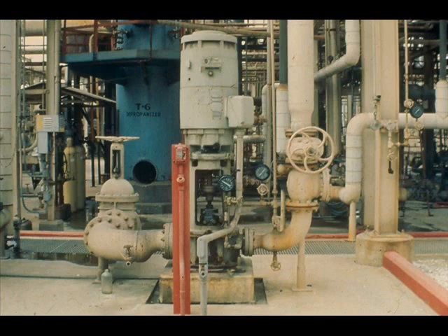In machines with vertical shafting, axial loads more or less are always encountered and are usually in one direction only. In addition to forces caused by liquid and gas pressures, the weight of the rotating assembly itself must be supported.